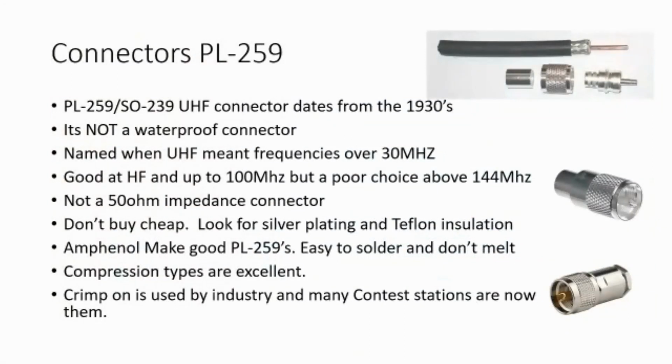So that's PL259s. Crimp on is very similar. You just need the crimp tools to put them on. Once you've got the tools, they're easy to fit. If you make up lots of cables, it's very handy to have the crimp ons, because it's quick and simple to put them together, and they're pretty reliable. Although I would always check them with a multimeter just to make sure you don't have a short.